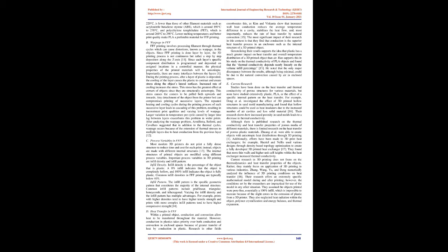SLS printing methods are used in direct metal laser sintering (DMLS) to melt and fuse powdered metal together with a laser. DMLS, SLS, and SLA, although having substantial capability, are expensive and are primarily only used in advanced industrial applications. FFF printing, however, is commonly employed in commercial 3D printers.